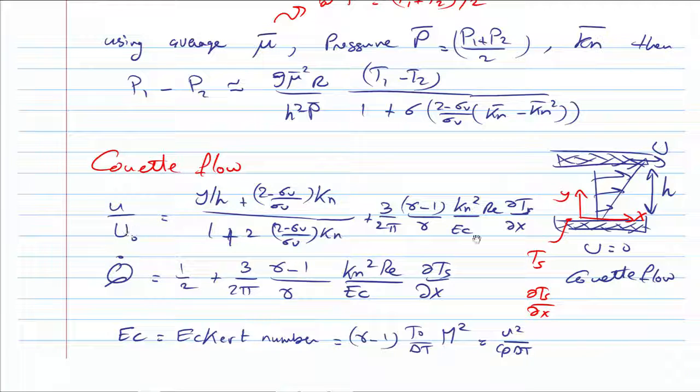Anyway, this is the temperature-driven flow, and this is the shear-driven flow. Both of them help if they are acting in the same direction. If one of them is against the other, they could even stop the other. Important note, look at this, the Q, which is the volumetric flow rate of a shear-driven flow, is half plus the thermal. Let's cancel the thermal for now. Let's assume there is no temperature gradient. So Q dot is half.